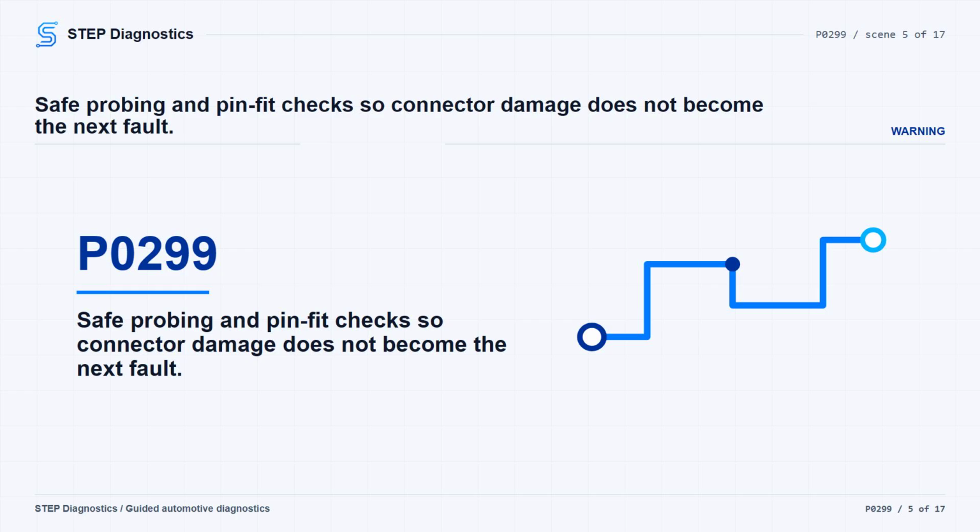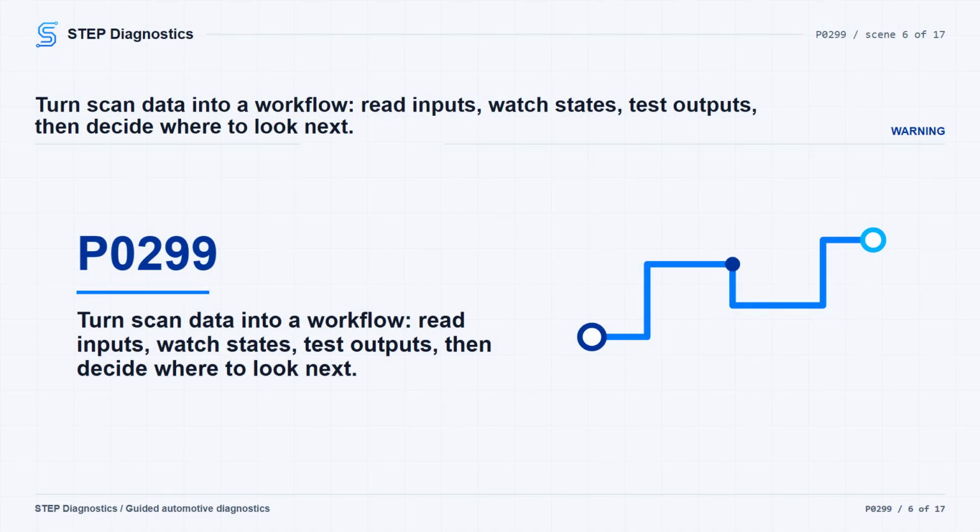If a small pin cannot be checked correctly because the connector hardshell, pin guide, or retainer is adding drag, remove the pin as needed for the fit check. Replace damaged connectors, pins, or terminals, and do not force test leads or probes into connectors, because that can create the next electrical fault. Use the scan tool to read PID inputs, output states, and diagnostic states.